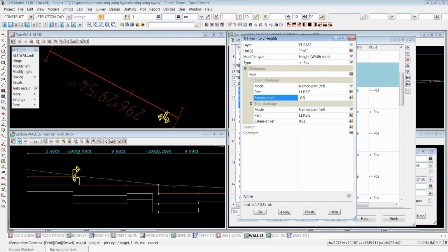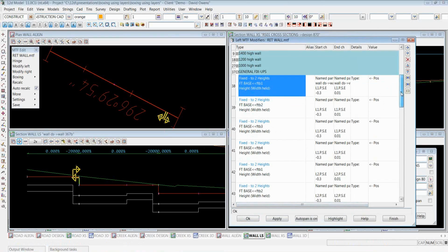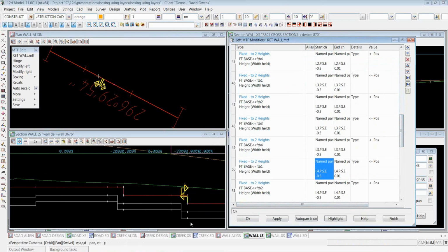Okay. So with this, I was able to get that extra thickness where the footings step from one level to another. So position backwards is very, very handy, but you really need to get those named parts in there, otherwise you're going to drive yourself mad, having to modify the changes all the time with these different parts. But once you've got one of them sorted out, it is just a case of copy and paste, work your way through all the different levels, so level 2, level 3, level 4, getting all these points just from a little bit beyond and pulling them backwards.